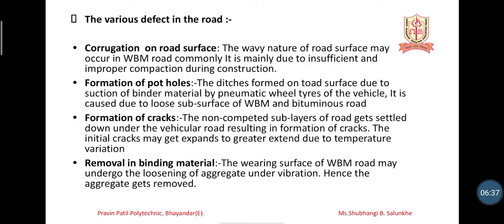Especially in a WBM road, if we are not properly vibrating and the loose surface or loose material is not compacted, then obviously it is going to be removed, and at that place defects will be formed because of the poor binding property of the material.